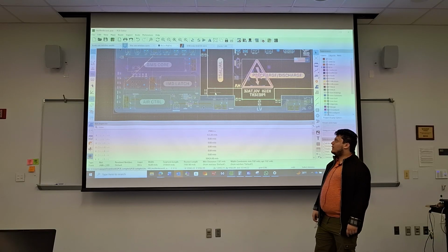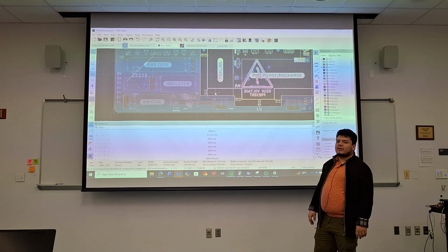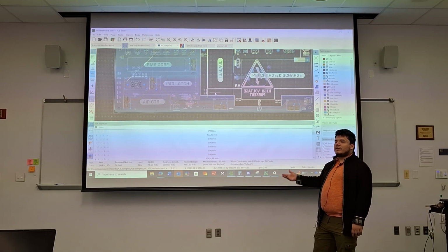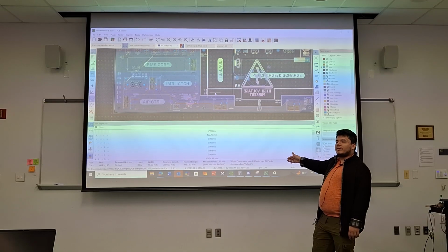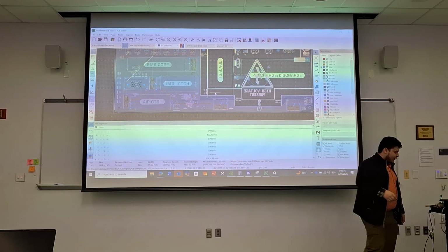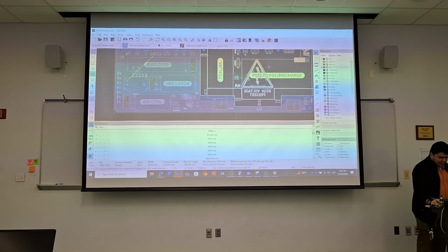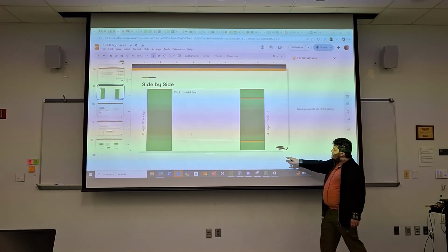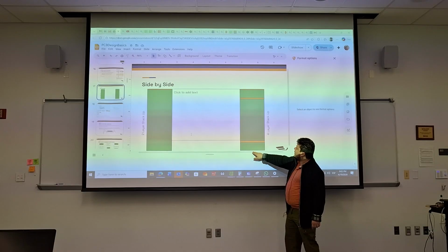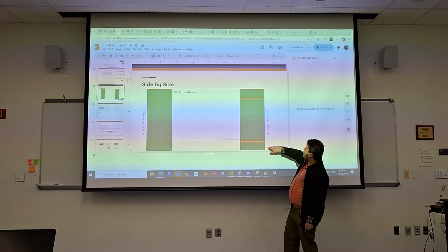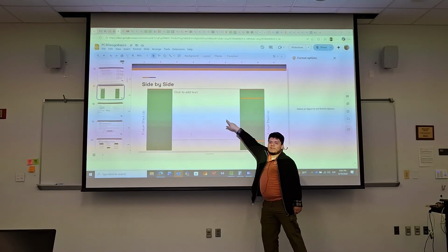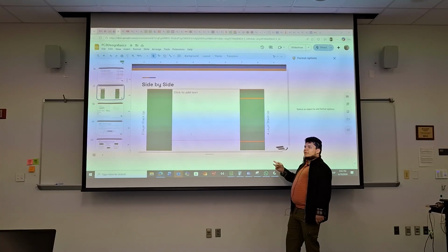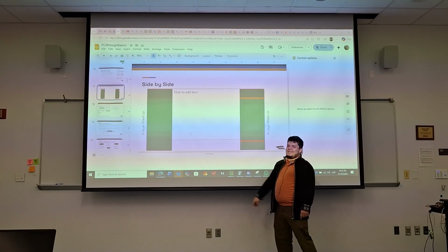And so if you're not referencing it correctly, you don't have any shielding because you don't have any ground below it. Your next ground is layer 2 and you're on layer 4. And if you remember the stack up, even though it's a 4-layer board, if you're routing down here, and your next ground is over here, and if you're doing that for 7 inches, or if you're doing that on the CAN and that's, what, 20 inches?